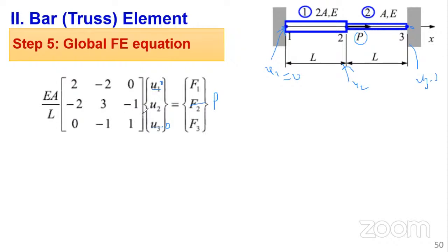So basically we said that to be able to solve this quickly, where we have a degree of freedom known as 0, you remove the rows and the columns associated with that. Temporarily, not that we are throwing them away, so that you'll be able to solve this quickly. So you're only left with the element related to U2. That is 3 U2 is equal to this P.